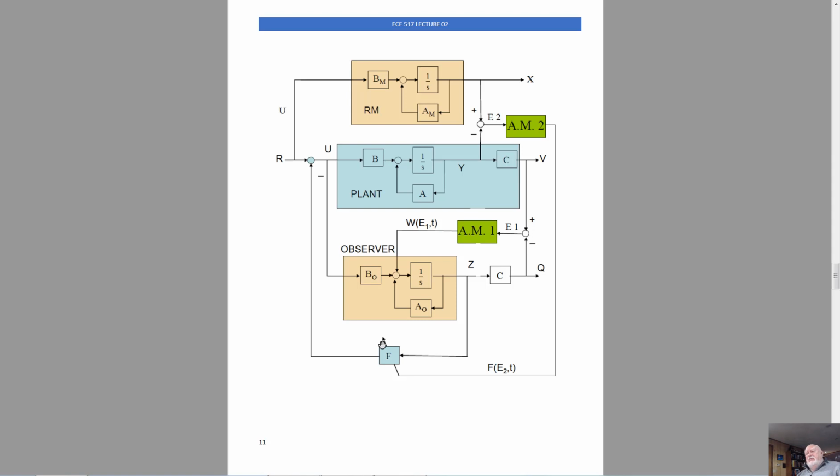So, take a look at the system. We have here two reference models. This reference model is the simulator that represents desired properties of the closed-loop system. It is consistent with the design specs. It's a simulator in the flight control computer. Now, the control plant with its controller is the adjustable system. The control plant, and I mark it with blue, and its controller represent the adjustable system.